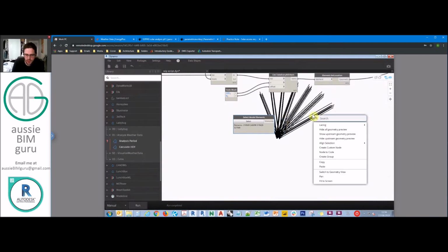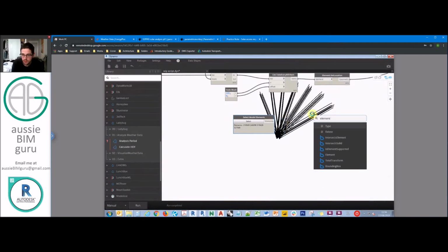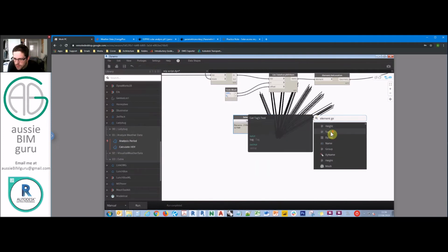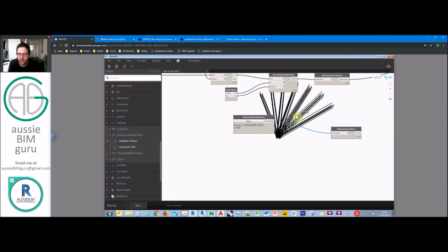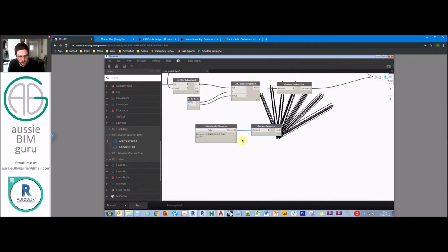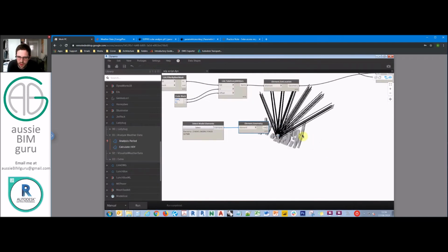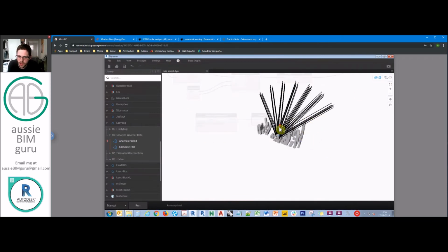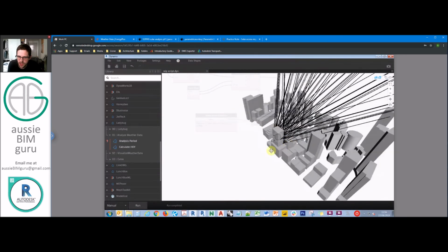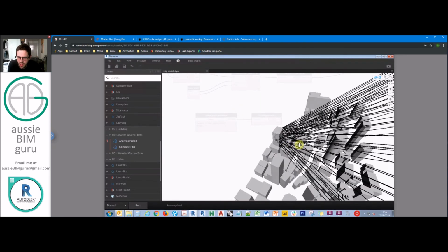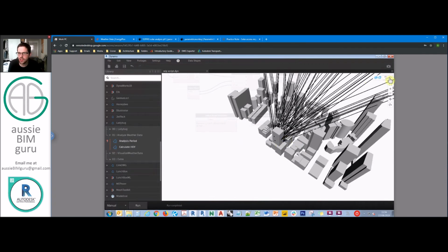Okay, so from that we need to get the element's geometry. It should be around here, this one here. As soon as we run this, we'll expect to see our site in Dynamo. So I'll run this and show you what we get. We should get a set of solids. So that's our site, essentially. And that's why I recommend modeling it in Revit, because it's much faster. You'll see that it includes the building mass as well, because we want to see where these actually clip the building itself. Okay, so you can see we've got a set of solids.